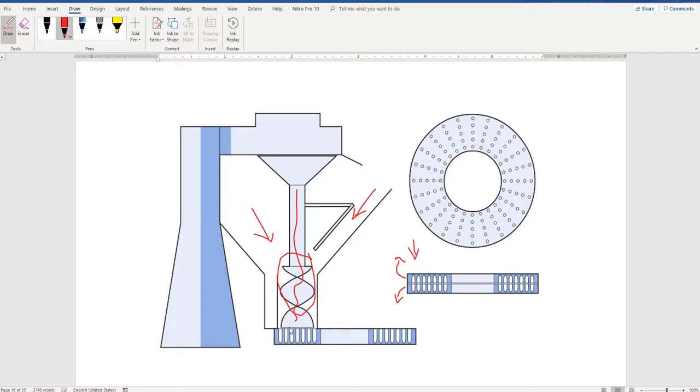Then manually you take the lower ring containing the bodies, you take them below the auger feeding system. Now the lower ring will rotate. While it's rotating, the filling of the bodies happens. When it completes one rotation, you stop the machine, you take this lower ring, and you take the upper ring, and you place them in a part of machine. Again here we do it manually.